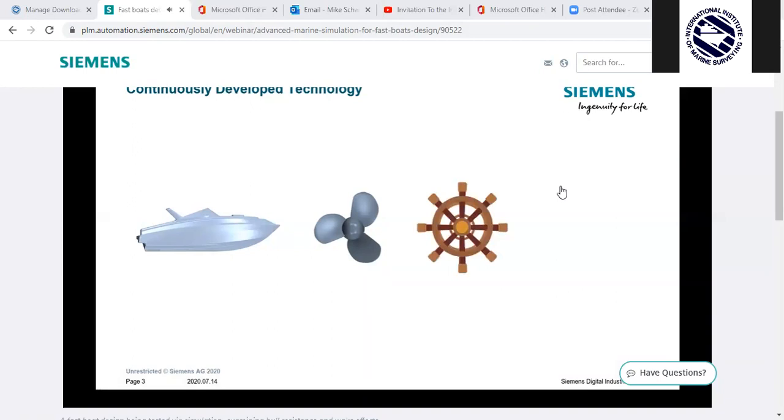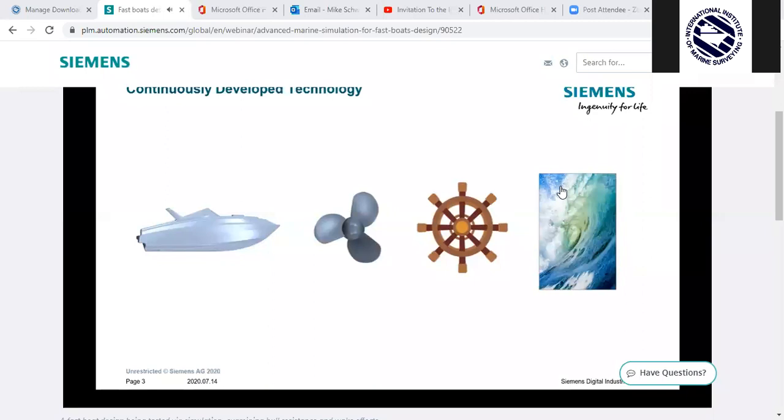And we have also added several features that would allow you to understand maneuvering characteristics. We can add in any rudders, stabilizers, control surface to help you understand how your vessel will perform in a free-running scenario. We also have dedicated modules to mimic any type of tow tank test, either at full scale or model scale. And we have also developed several ways to model waves, and we have ideas on how to handle just about any type of seakeeping scenario you may be interested in.